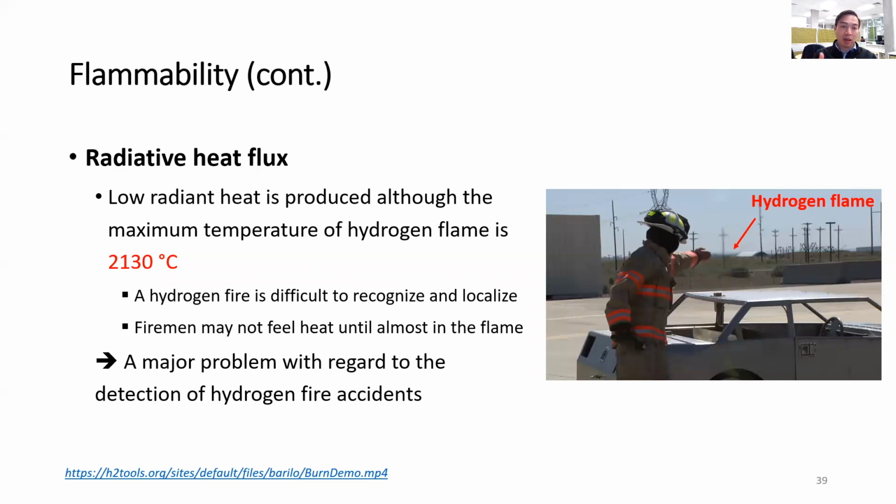And this is actually a major problem when we're talking about detection of a hydrogen fire incident. Case in point, if you look at the imaging on the right side, the fireman can actually get very close to a hydrogen flame with his bare hand without feeling any pain just yet. But it is really dangerous because you would be in the flame before you even know it.